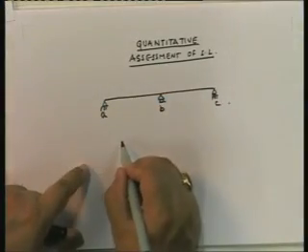Okay, and that is not a very efficient way. You can do it, I'm not saying you cannot do it, but it's not an efficient way of finding out an influence line, because in an influence line, all I'm interested in is what are the ordinates of the influence line so that I can find out the particular response quantity. And the best method which directly finds out the bending moment at B without finding out something else is the moment distribution method.